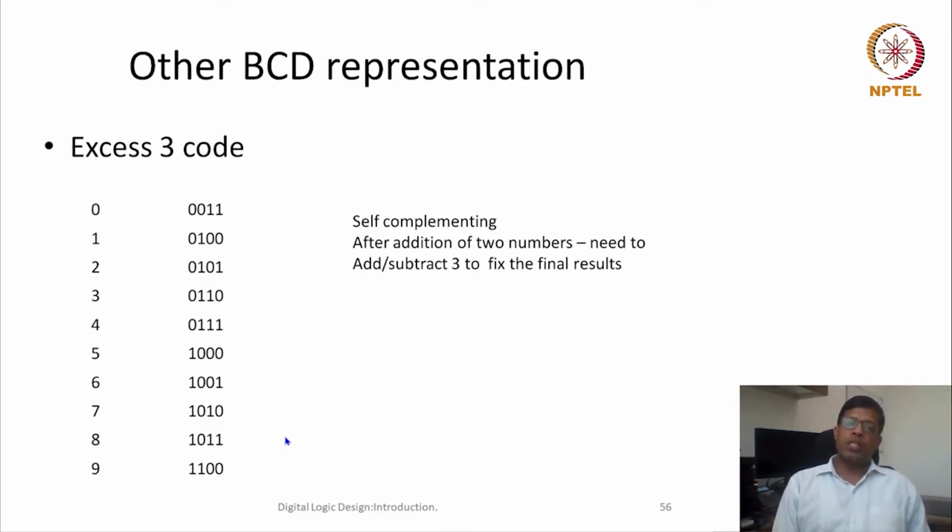According to hardware design, it is found to be simpler if addition and subtraction is done using this XS3 code. One more thing we have to understand is that all of these codes are mostly invisible to the software developer or the end user. It's only an internal hardware representation, so it doesn't matter whether 0 is represented using 0000 or 0011.